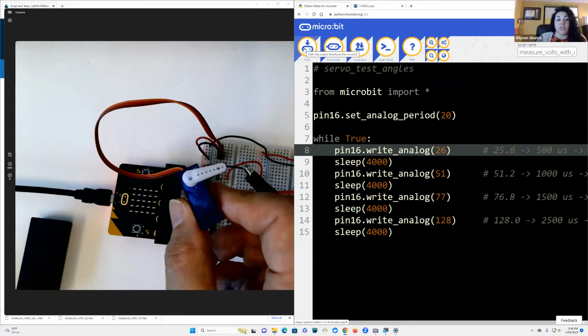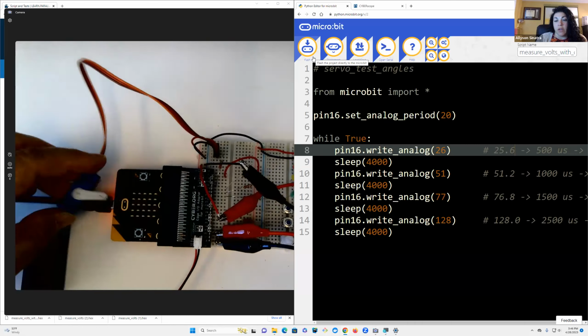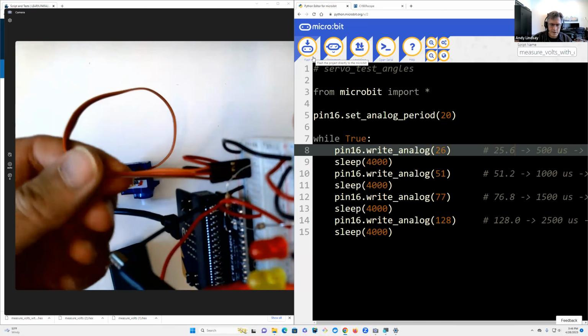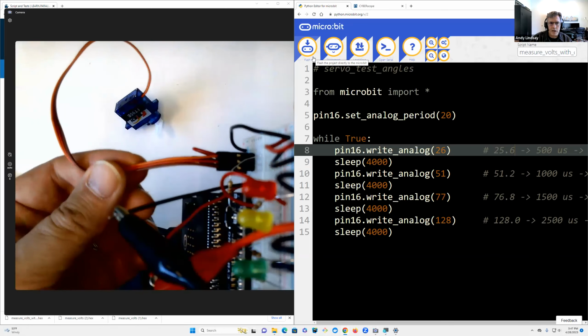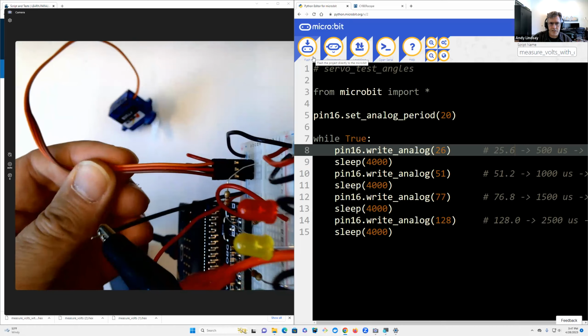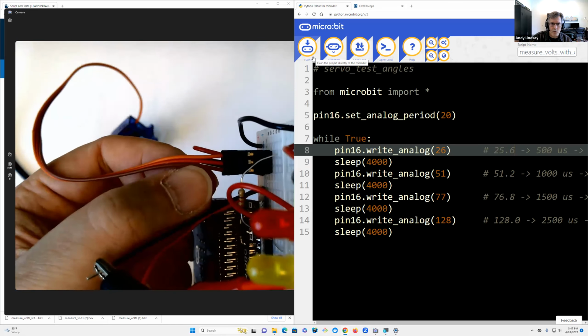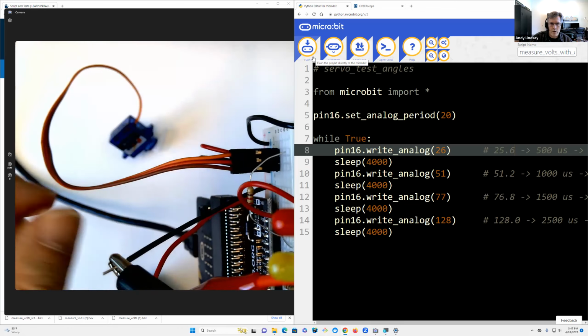My students also, when they have this, it's usually when they have the servo wires backwards, like the yellow, orange, brown. Yes. They'll have those backwards. Thank you. Excellent point. So that's definitely a thing. You want to make sure that the brown wire is low and the orange wire is up high.